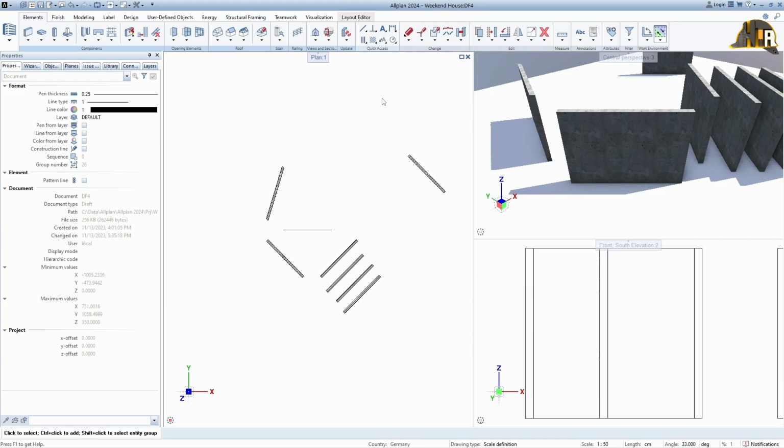In every BIM software, including this one, all 3D elements that we model are linked to some imaginary planes. Those planes extend into infinity, and with their help we easily determine the position of our 3D objects. In Allplan, the tool for controlling those levels is called Floor Manager, and we're going to create our level structure.